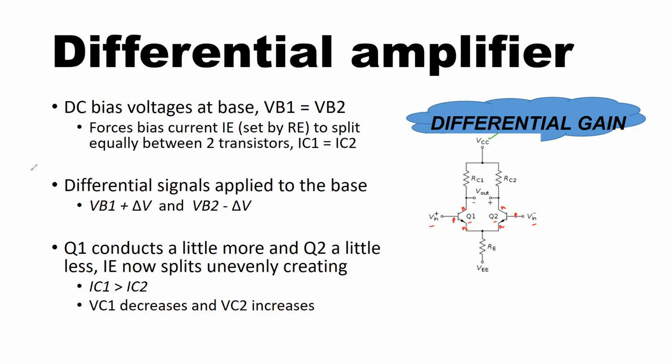And let me also highlight the terminals. That is the collector pin, this is the base pin, and that's the emitter pin. This is also a collector pin, this is the base pin and the emitter. So the emitters of both of these transistors are shorted together, as you can see. And now, before I apply time varying signals, I need to bias the base of these transistors Q1 and Q2.